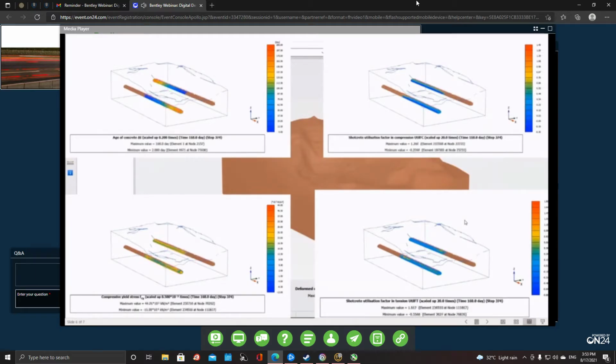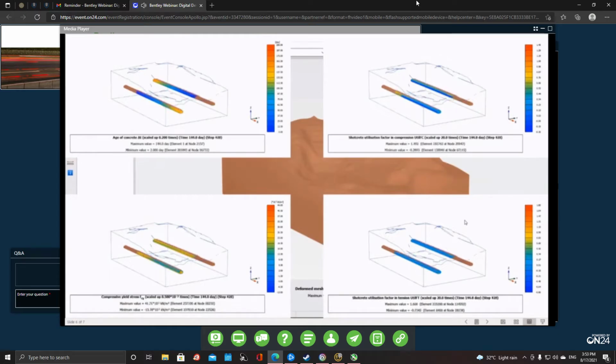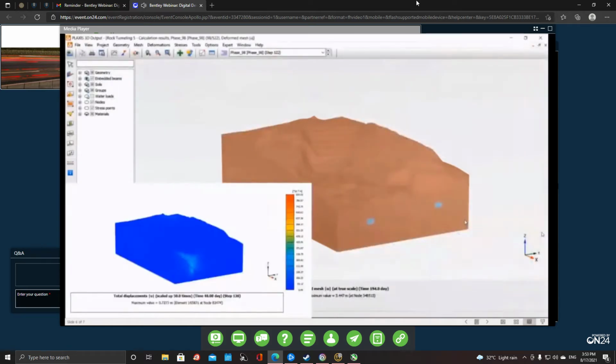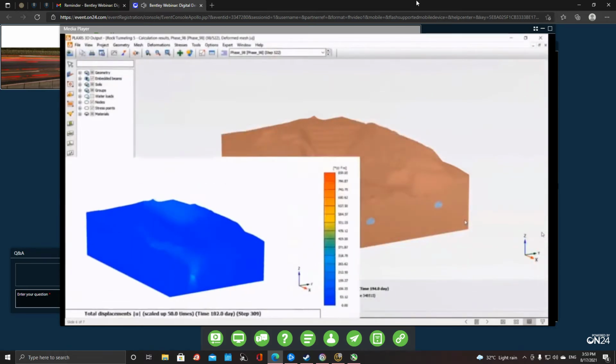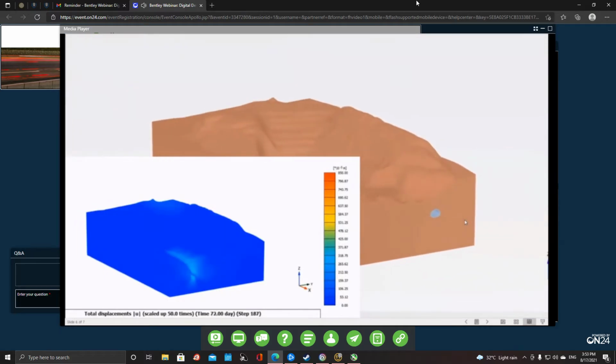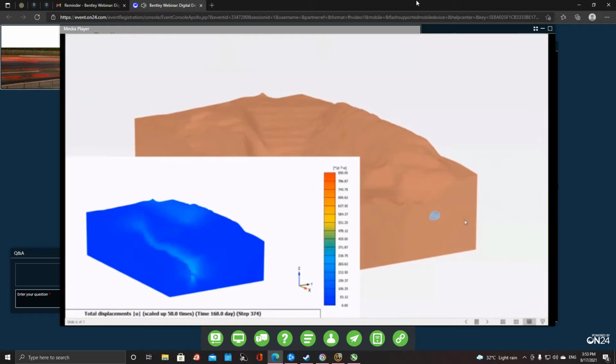Sequential excavation method, often known as NATM, the New Austrian Tunneling Method, involves a sequence of construction activities in a typical cycle. The method has a lot more flexibility in the sense to accommodate large diameter, arbitrary shaped tunnels in rock formation. Drill and blast is often used in conjunction with this method, whereby support for excavation is realized by means of shotcrete, rock bolts, and forepoling. All these features, so are the series of time-dependent behaviors, can be incorporated in a single model in PLAXIS, just like that.